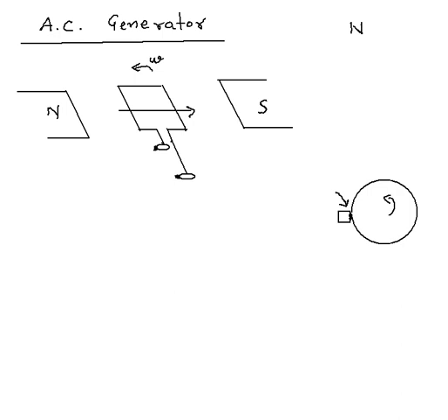You are going to connect your external circuit from these 2 points. So an external wire connects this carbon brush, and an external wire connects this carbon brush. You connect whatever you want across these 2 fixed brushes, and that thing will get electricity. How will it get electricity? When the coil turns, its area vector makes different angles with the magnetic field.